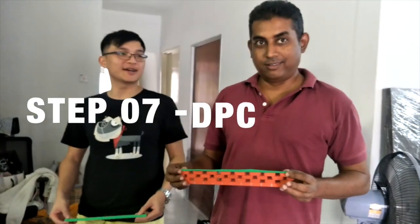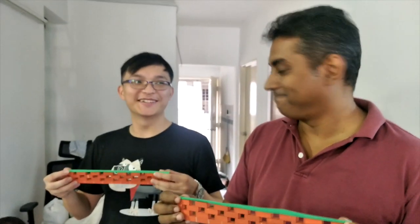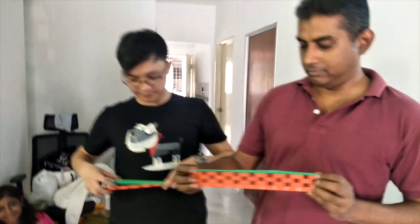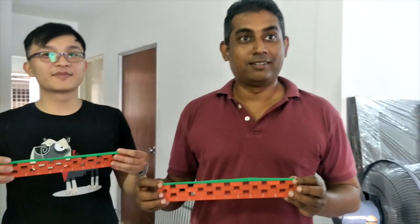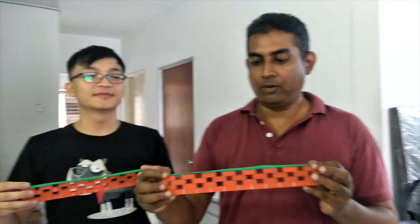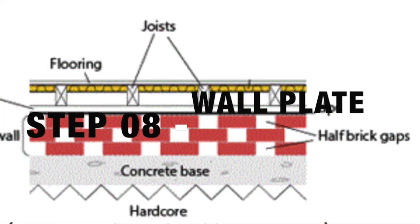DPC is a barrier through the structure designed to prevent moisture rising by capillary action, also known as rising damp. DPC is usually built into walls, typically 150 millimeter above the ground. There's a lot of materials available, but again the thickness varies because it depends on what material is being used, but generally 50 millimeter is required. On the working model, we are using green foam sheet and we layer it on top of the honeycomb slipper wall.